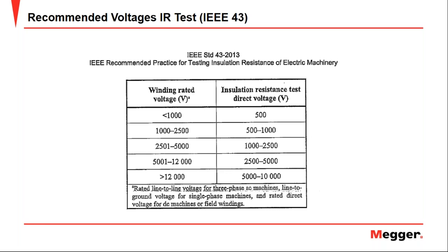Okay. The next question. What is the diode test used for? Oh, okay. When you have, for example, a rectification bridge, you need to know with certainty that all the diodes in the configuration of the circuit are working fine, because otherwise the outcome will be whatever.